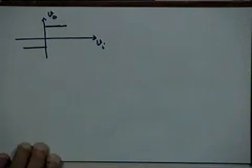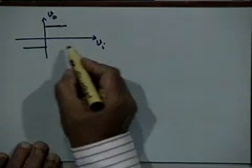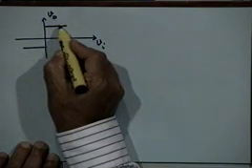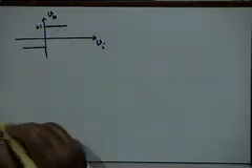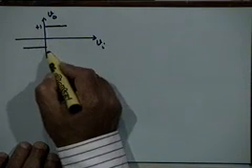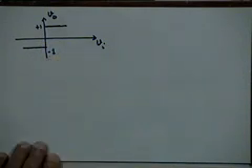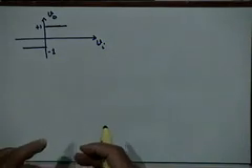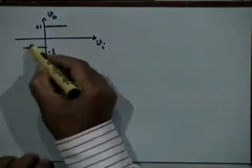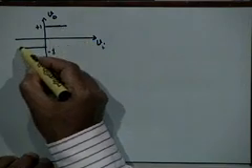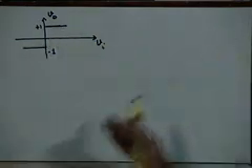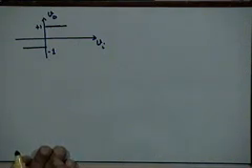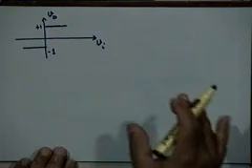This is what the characteristics are. If the input is even slightly positive, the output becomes 1. If the input is even slightly negative, the output becomes minus 1. That is the definition of a hard limiter. As against hard limiting, we can have a soft limiter which goes something like that, right. It also limits ultimately, but it does not limit the moment the signal becomes either positive or negative. It carries out that operation more smoothly.